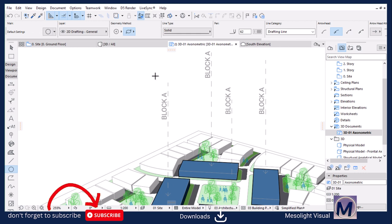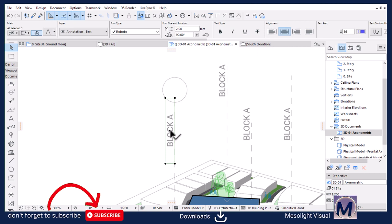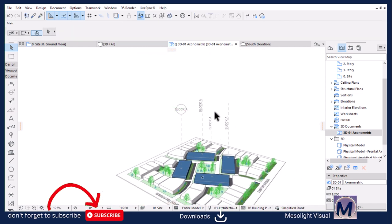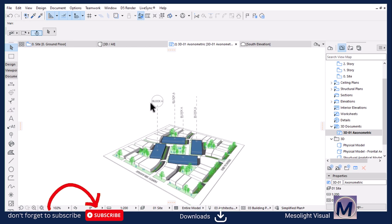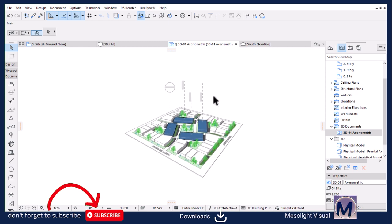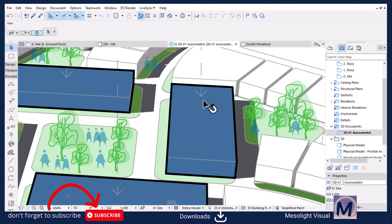Or we can make a bubble. This point of choice. A bubble like that. Move it there. Rotate this to horizontal. Insert it in the box or in the bubble. Let's see. Let's increase the bubble. Something like that. You can trim off that line. Perfect. So it depends on how you want to do some annotation, and if you want to add depth as well,